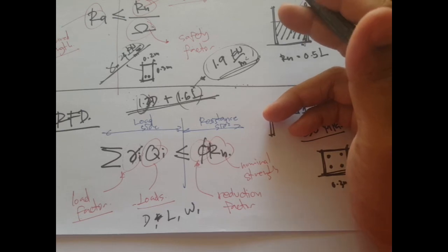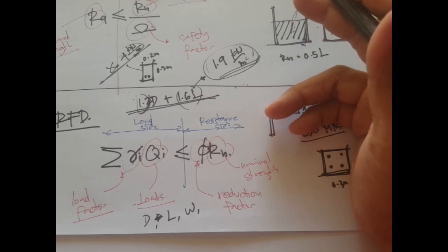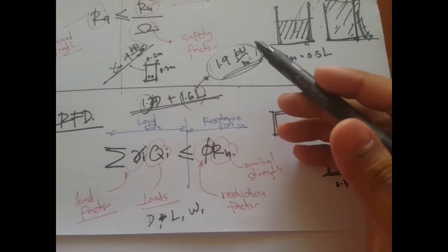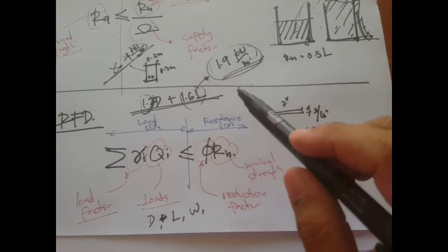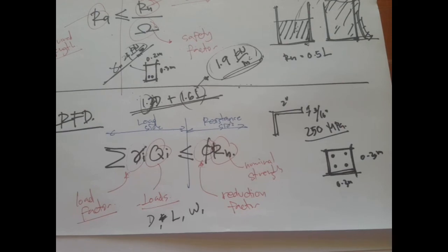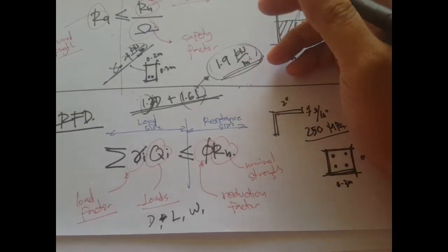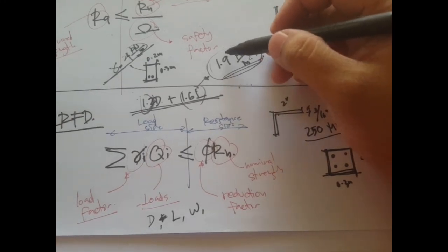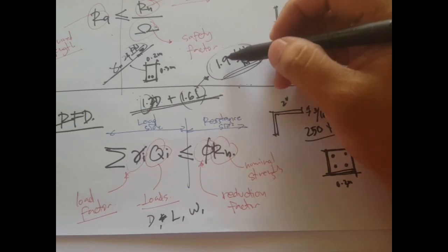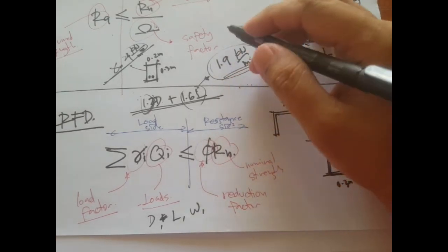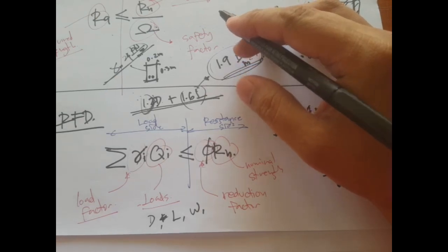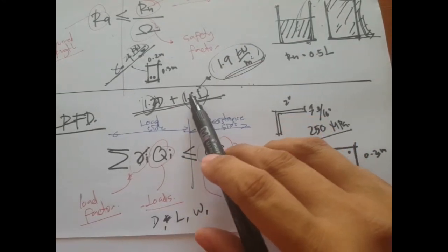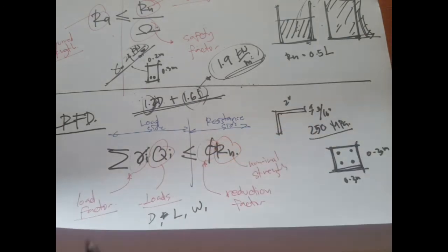Or probably instead of just having soft activities, there's going to be some movements, or, let's say, if there's an event, then there's going to be some party or something like that. So the loadings could be more than that. So the point here is, because there are larger uncertainties in live loads, we have a larger value of these load factors.